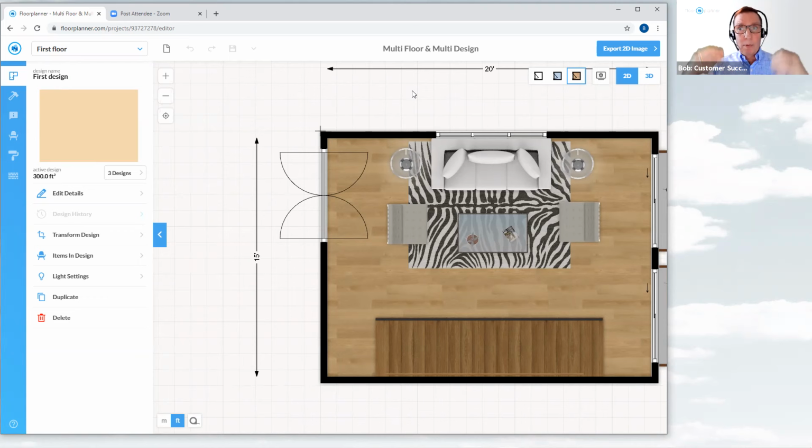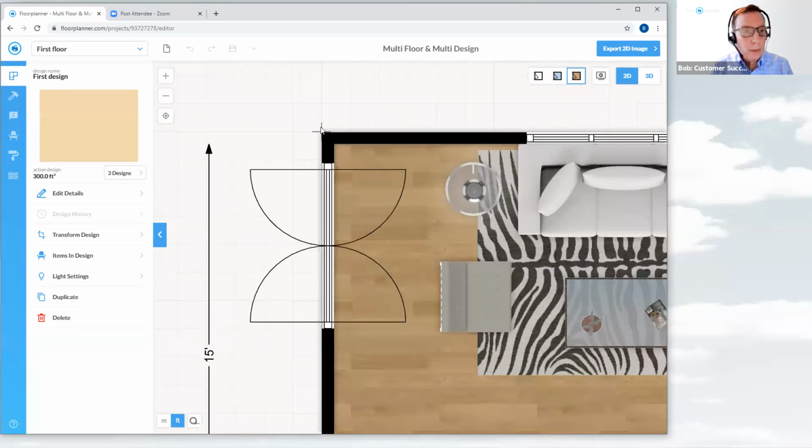the first floor above to be my second floor, keep the same structural walls, the same load-bearing walls, keep them in place, don't move them, and delete the excess on my second floor, and then create the rest of my second floor. That way I know for sure everything's completely aligned with each other. Or if you had any difficulty afterwards, like I said, you can go ahead and relocate this plan to be closer to this origin point.